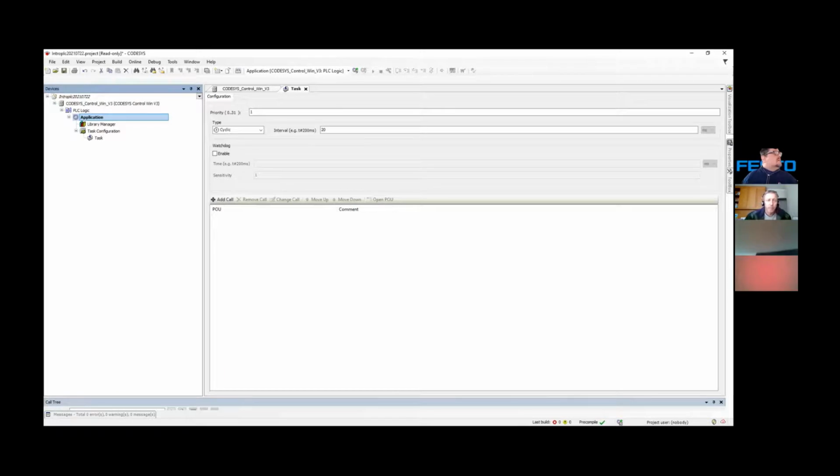Thank you. Okay, right, guys. Now, within the application, can you see application on this? Yes, I can see application on the left-hand side. Okay, excellent. All right, guys, now check what happens within a task configurator itself. I'm going to add my program by right-clicking application, then click add, and I'm going down to POU. Right, what is a POU? Like I've mentioned to you, it is program organization unit. Now here we can select all the languages that I've mentioned to you earlier on. I'm going to select now the ladder diagram language.